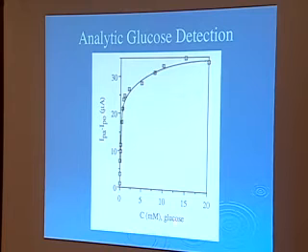And we're actually going over a regime here, from 0 millimolar to 20 millimolar. That goes way over the physiological regime, unless you're seriously ill. And you can see that we have two regions. We have a low glucose concentration region and a higher region that we can both linearize if we want. So we have a nice sensor system, as long as you tell me which region you want to look in. This one down here, if your glucose levels are that low, then you're not breathing, or breathing too much or something. You need more glucose than that; you're in diabetic shock if you're down there. So it actually turns out this slope up here is the important one.